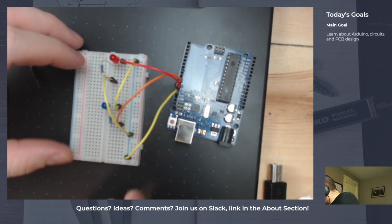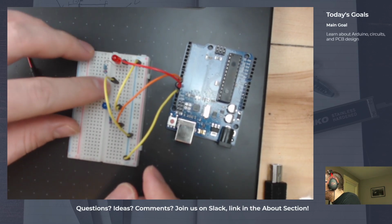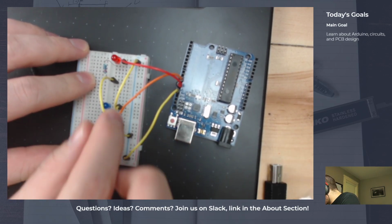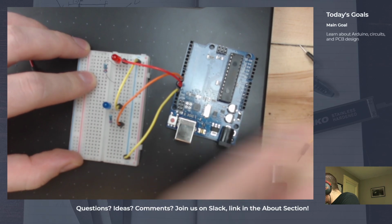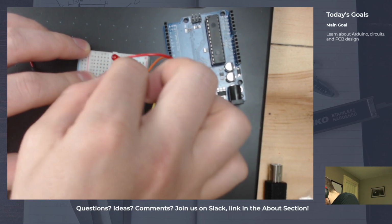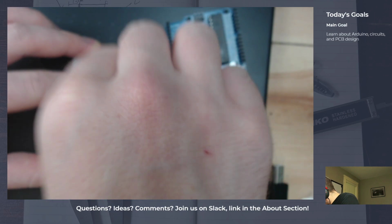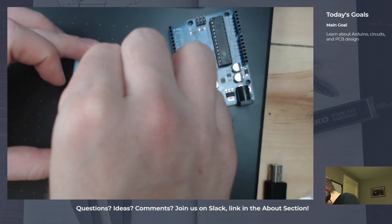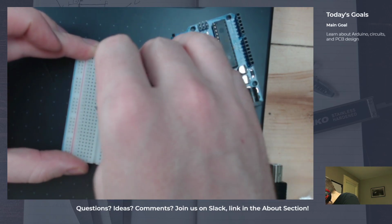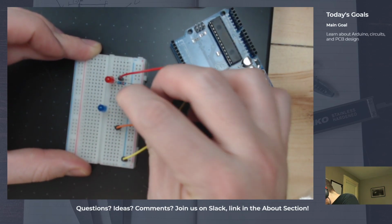So what we can do is, resistors can act as kind of like wires. On either side they have wires. So we don't need this yellow wire. We could actually plug one side of the resistor straight into ground. So if we get rid of this wire and get rid of that wire, put them out here, we can just take one side of the resistor, plug it into ground, and now we've just removed one wire from that little setup, and we can repeat the symmetrical thing. We repeat that process.